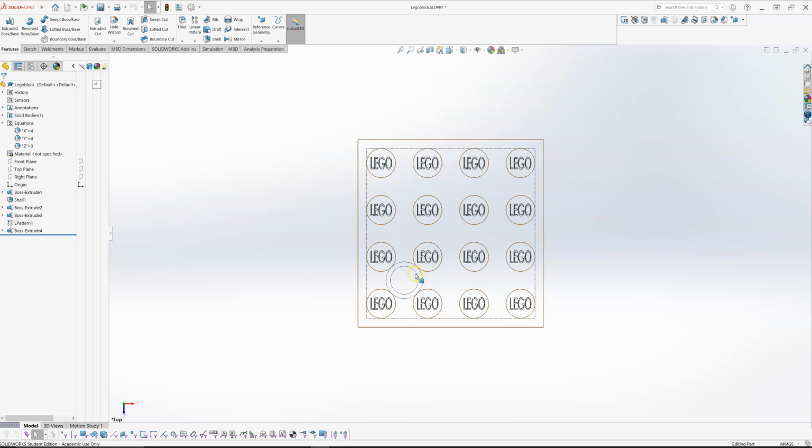I want to create this such that in this case here, let's say there's four Lego units or 4 studs on the top. I'll need 1, 2, 3 studs on the inside. And the number of internal studs is always going to be 1 less than the number of outer studs. So if you've got 6 Lego units across the top, you're going to need 5 studs on the inside. Similarly then in the Y direction as well.